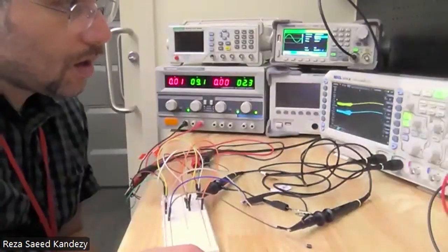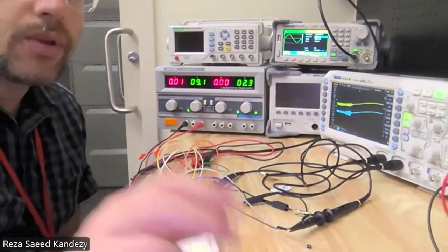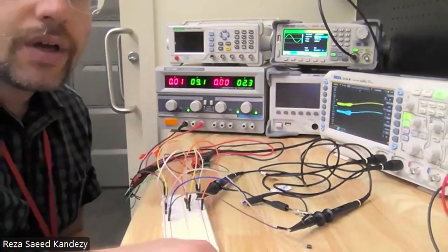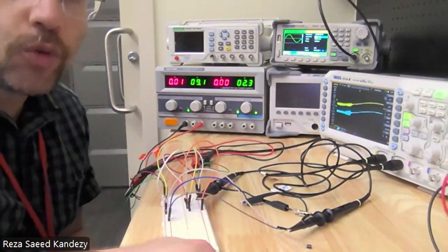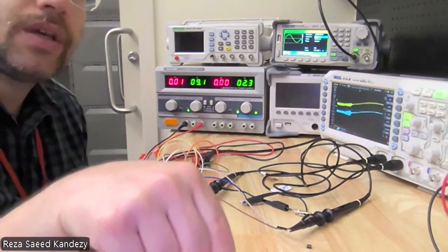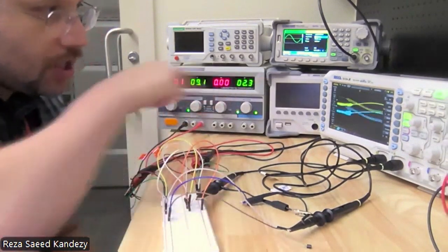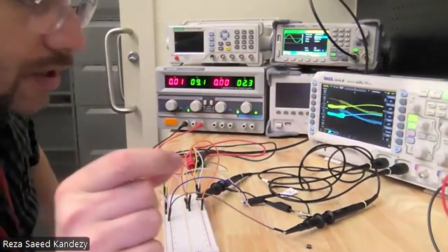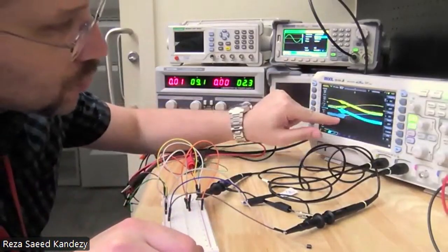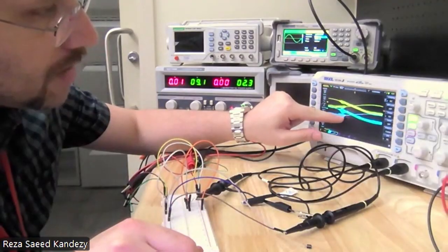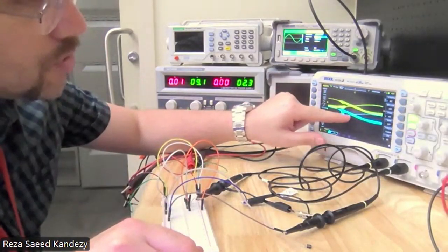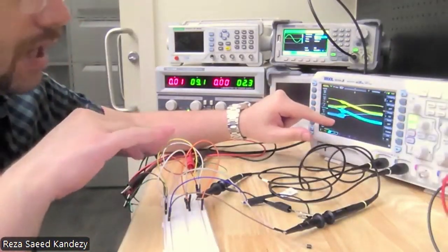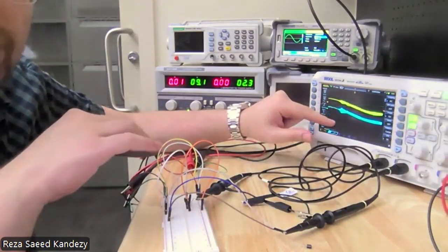Now, let's see about the distortion that we talked about. In simulation, you can create a very clear waveform, so it's easier to calculate the distortion signal. But here we can't see exactly the distortion equal to 0, but you can see the distortion happening at this area. So we have a pure sine. This double vision is because of the noise that I have. I didn't have any capacitor or any filter in my circuit.